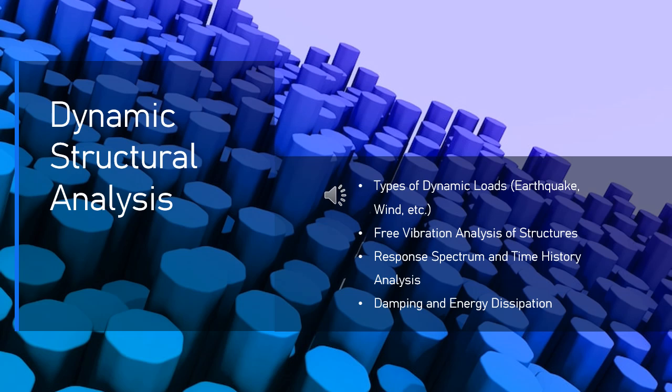1. Horizontal loads. These are the lateral forces generated by horizontal ground shaking, often the most critical component. 2. Vertical loads. These forces arise from vertical seismic movements, which are less common but can still have an impact, especially on tall structures or critical systems. 3. Moment loads. Earthquakes often induce torsional moments due to the uneven distribution of forces or irregularities in the building's shape. Earthquake analysis methods. Response spectrum analysis.